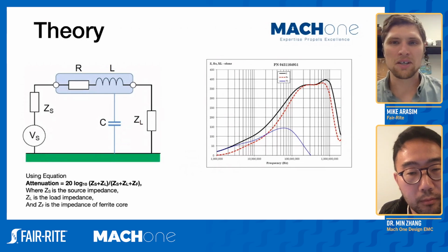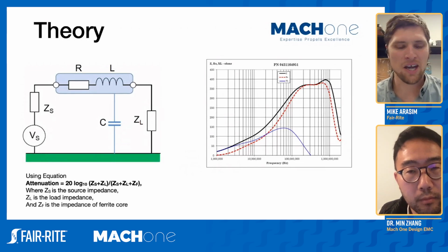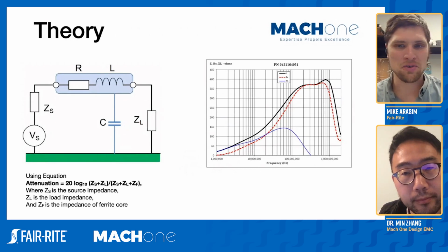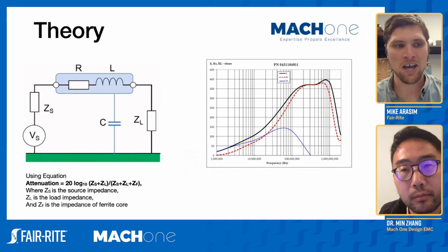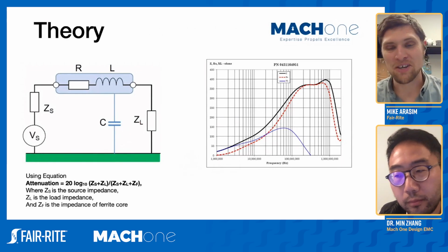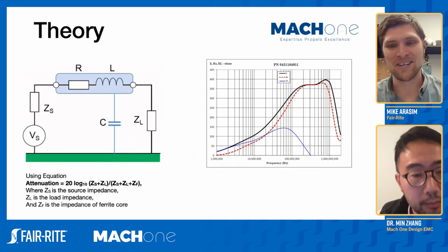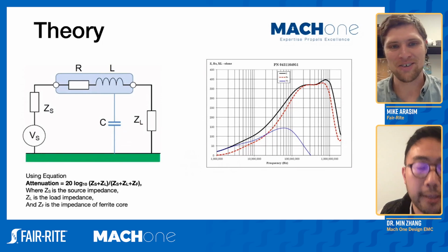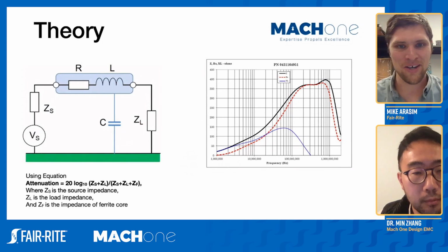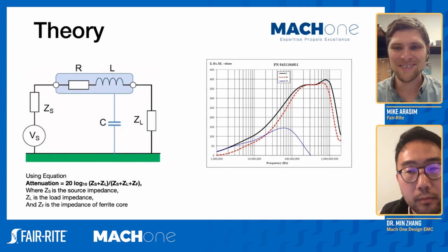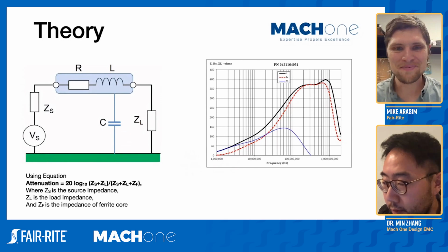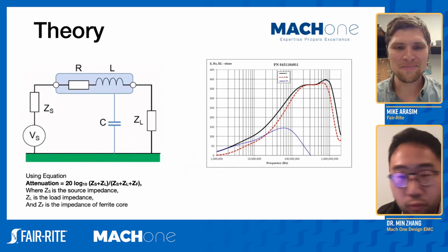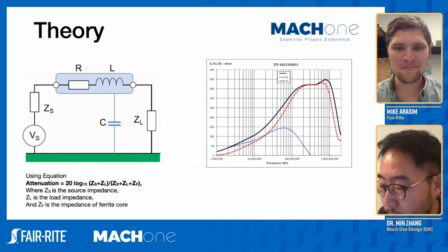You do at times by way of caring about that absolute impedance. Typically, there's not going to be too many applications where you're deliberately designing to have a high reactance with a ferrite. Well, speaking of suppression applications, now if you're trying to make something like an inductor or transformer, you absolutely want that high reactance, and ideally you want R sub S there as low as you can get it. Okay. So that's about the theory of a ferrite core.